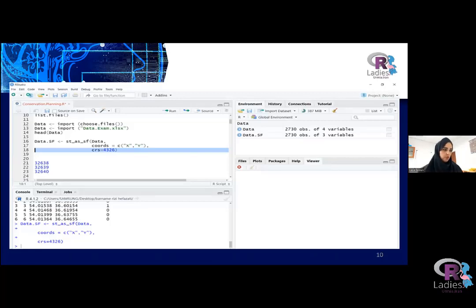According to this form, our data has been converted into spatial data. These numbers, noted below in the command line for converting spatial data, indicate the zones inside the country. Iran is located in the 4 main zones, 38, 39, 40, and 41.